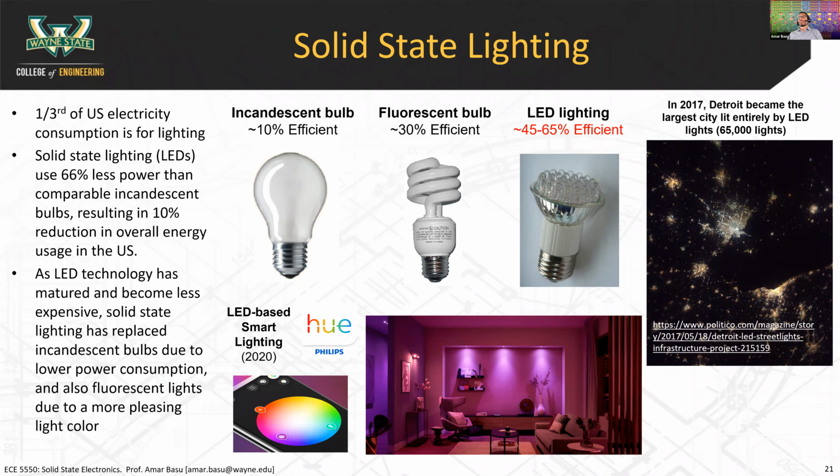That discharge is absorbed on the walls of the fluorescent bulb, because the walls have these things called phosphors on them. There's ultraviolet light generated inside the fluorescent bulb. The phosphors absorb the light, and then the phosphors put out their own light, and that light is in the visible spectrum. If you go to a tanning salon, they have fluorescent bulbs that don't have the phosphors on them, so they just radiate ultraviolet light everywhere, and that's how you get a tan and skin cancer.